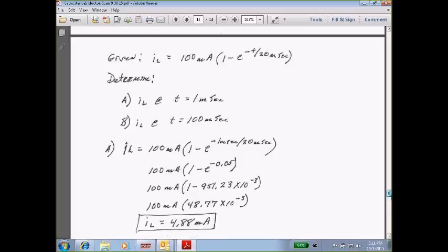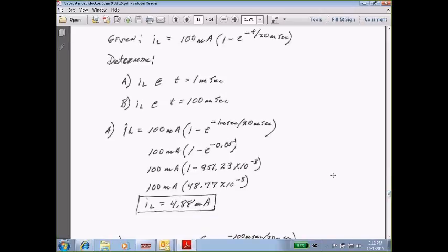Okay. In the lab, I have the students put together a model of an ignition system for a car. What I use for a spark plug is a neon lamp. The ones that I have in the lab take anywhere from about 60 to 80 volts to fire. I give them a 9-volt battery, and they have to be able to fire that neon lamp. So they need a coil. The ones that I have available for them is an 8 Henry coil.